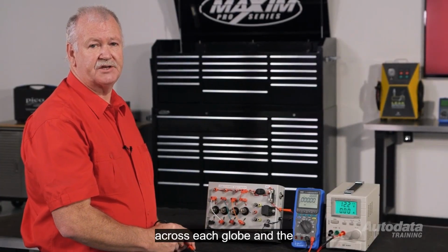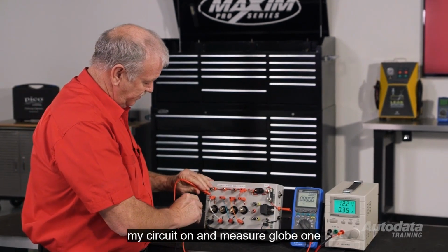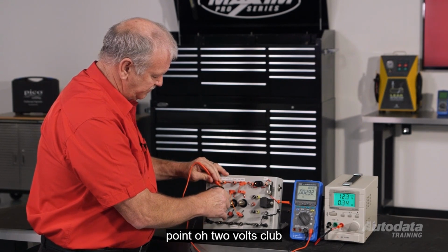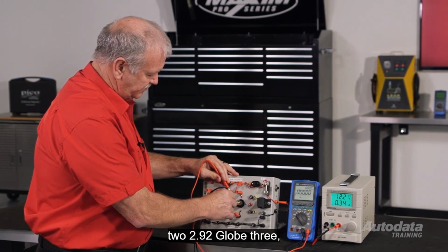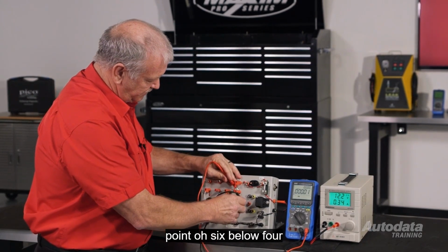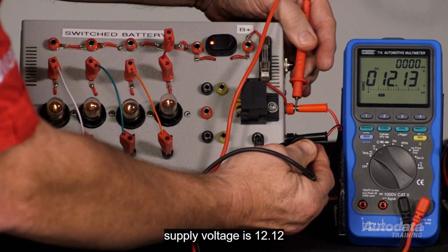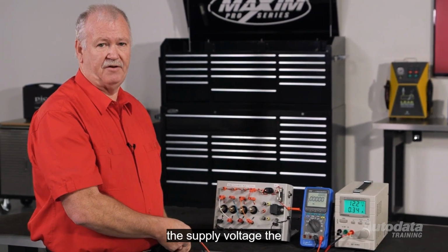We'll measure the voltage across each globe and the supply voltage. I'll turn my circuit on and measure globe 1. 3.02 volts. Globe 2, 2.92. Globe 3, 3.06. Globe 4 is 3 volts. And the supply voltage is 12.12. As you can see, the individual voltages add up to the supply voltage.